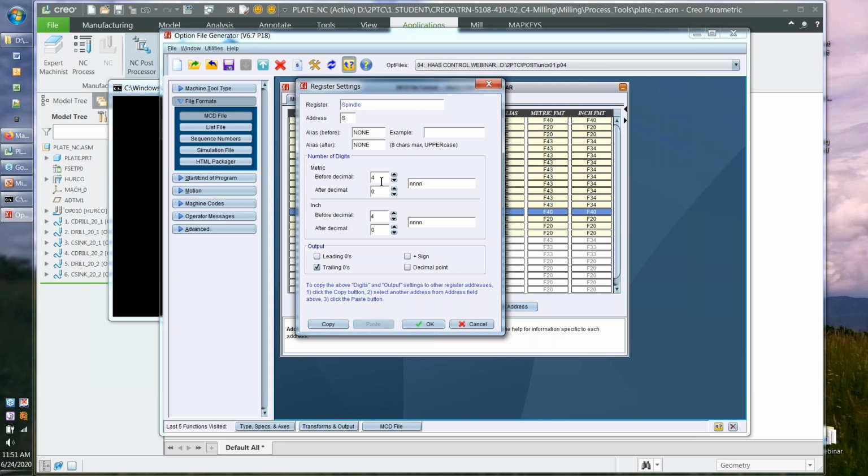We would output trailing zeros, but we are not outputting the decimal point. So that, it's kind of like not effectual for trailing zeros in this case. Arguably, in most cases nowadays, you ought to bump that up to 5 digits unless your machine doesn't support that. It's getting to be more and more typical that we're exceeding 10,000 RPM spindle availability on most machines.